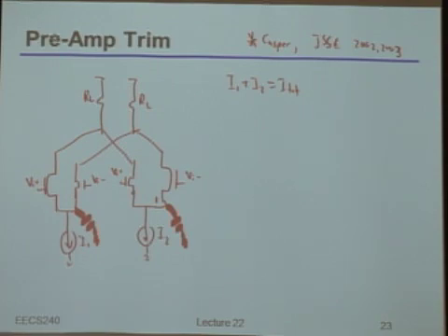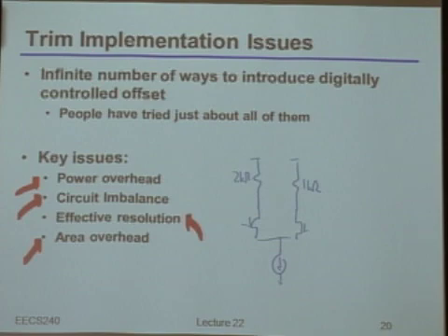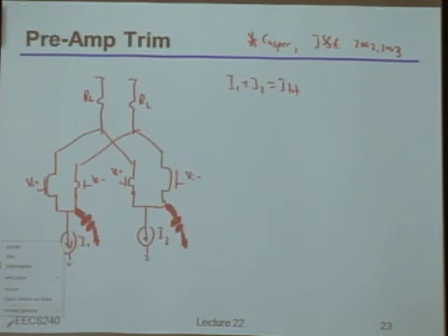Yeah, exactly. It's horribly asymmetric, right? So you guys thought I was joking, but if you recall, the first thing I showed you was something that looked like this. Well, guess what? I just did it, right? Because if I really needed a large offset range, I intentionally put this whole circuit in a way that basically had a really big inherent asymmetry in it. So issue number one with this particular thing is indeed the asymmetry when you have large V offsets.